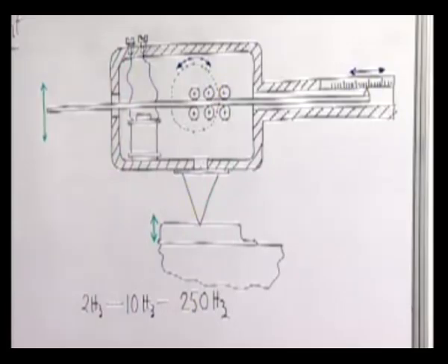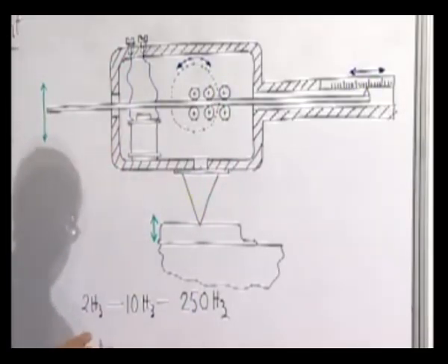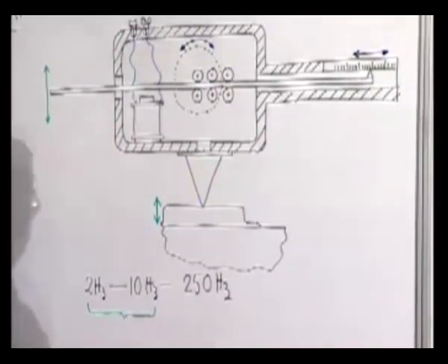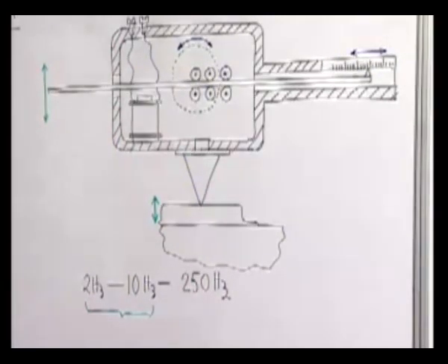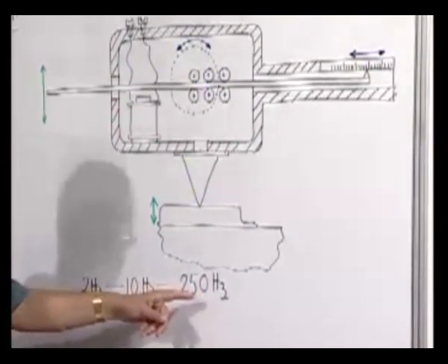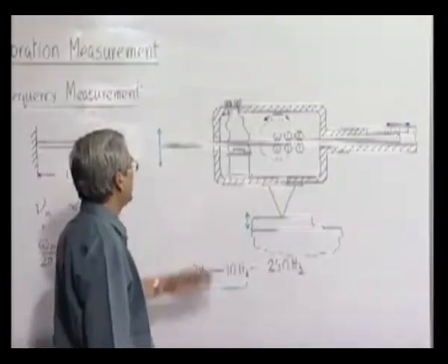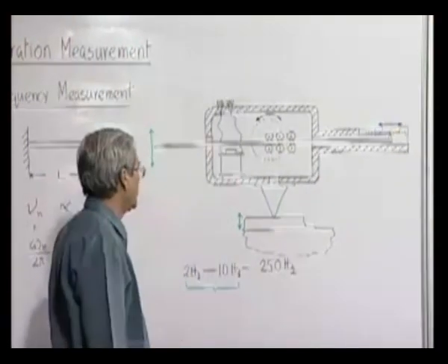However, when we use the lower range, a standard mass is attached to this, because otherwise the range is so large that it would be essential to change the length of the cantilever portion to a very large value, and it will make the length of the whole equipment very large, which may not always be desirable.